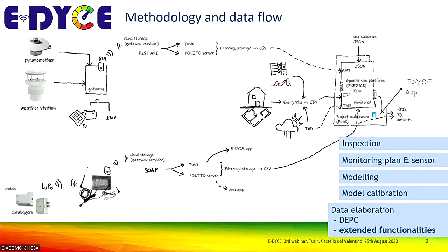One of the things that we pursue, similar to what was done in the other demos, but clearly each national background will support minor changes in the approach, is based on deep inspection of the demo cases, to prepare and produce a monitoring plan, and the installation of sensors able to connect to the cloud and support real-time measurement inside the buildings: energy, electricity consumption, but also temperature, CO2, relative humidity, and other thermal comfort or visual comfort aspects inside the building.